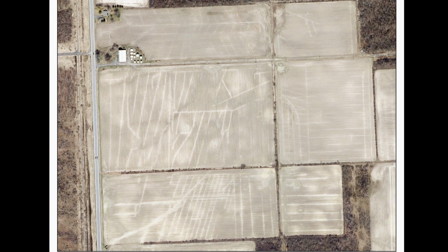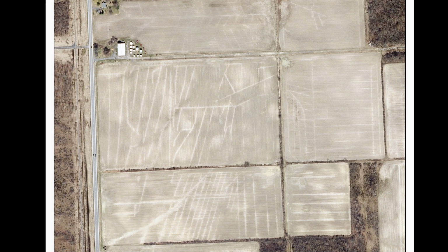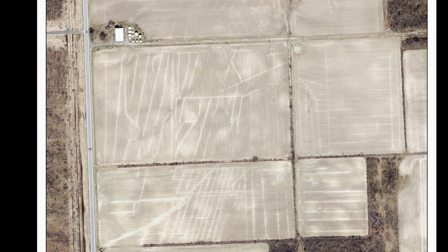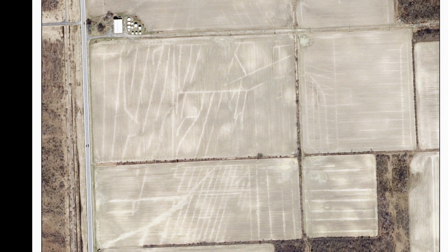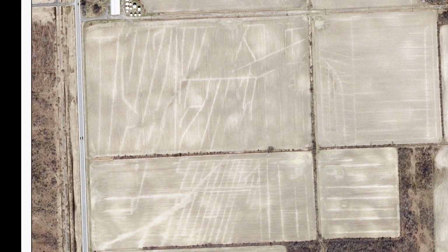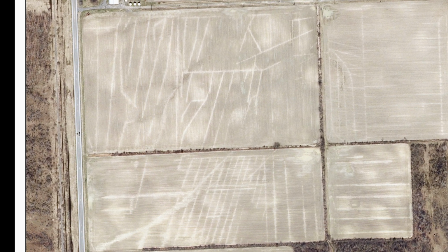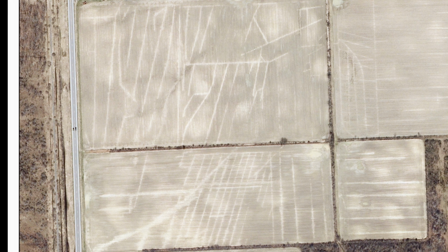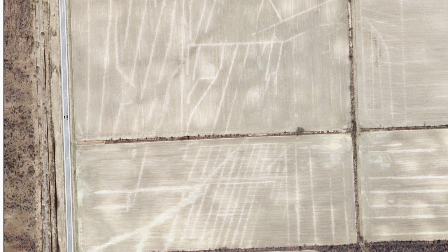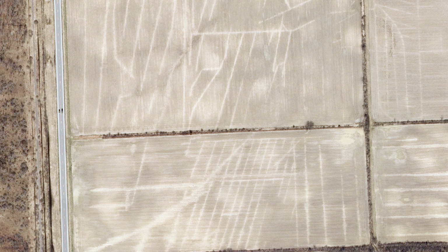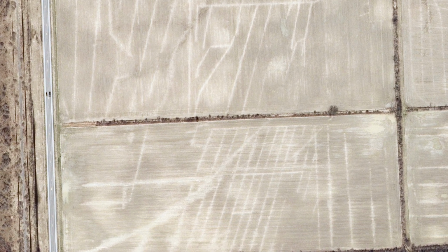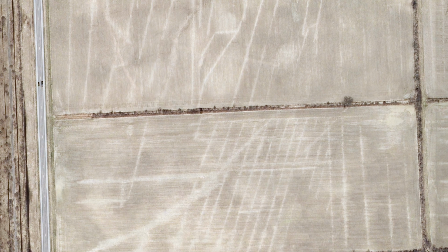Here's another aerial photograph taken in Seneca County, New York, and again you can see where the buried drainage structures are located. I want to emphasize how rare it is to be able to spot buried drainage structures in an aerial photo. However, these photographs should give you an idea of the high number and the high density of structures that are used to drain wetlands. This is why it's of critical importance that you dig a core trench and build a groundwater dam for every wetland project that you design.